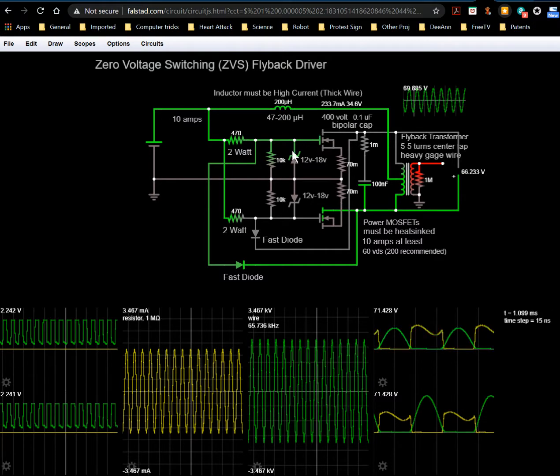So if you're ever using a constant current source driver, like in an LED application, for example, that has CCS drivers in it, you'll find that it's easy to calculate these things because it's a constant current source. It can't draw any more current than that CCS will allow, so the charge curve actually becomes very linear when you have something powered by a CCS. That's just an aside, but it's a point that this really is a genuine capacitor. It's actually a real capacitor.